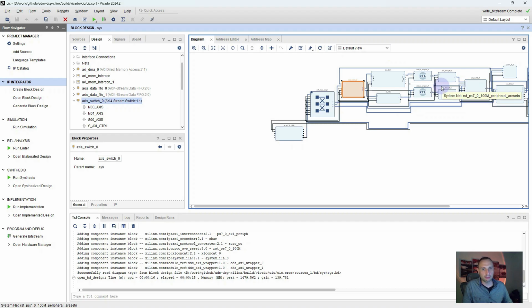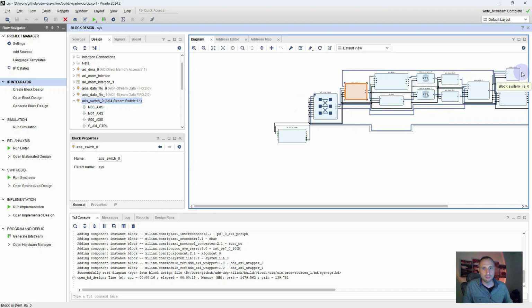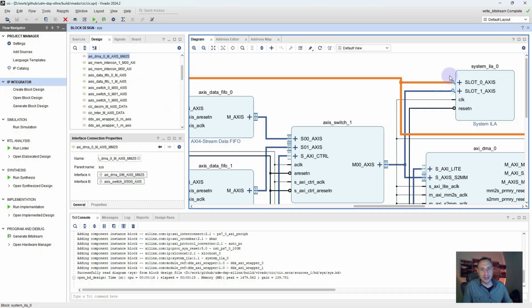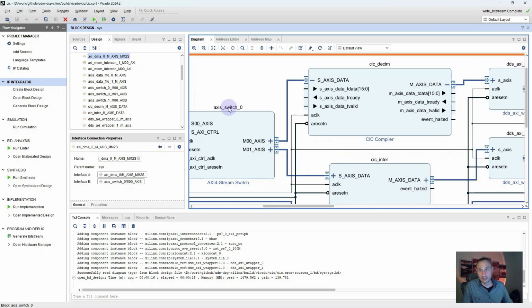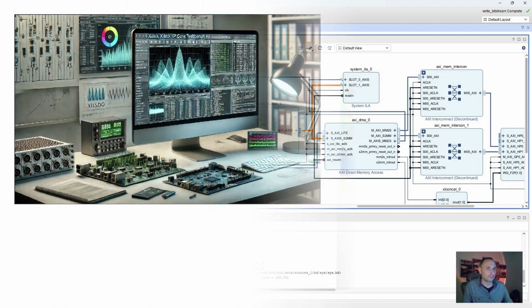Let's run the Vitis project in order to generate the platform component and the embedded C application from the exported XSA file. Also, here I failed to mention that for debugging purposes, I have a System ILA, an integrated logic analyzer, with AXI-Stream ports connected to the XDMA output and XDMA input. So it allows me to check data transfer for input and output of the IP cores.